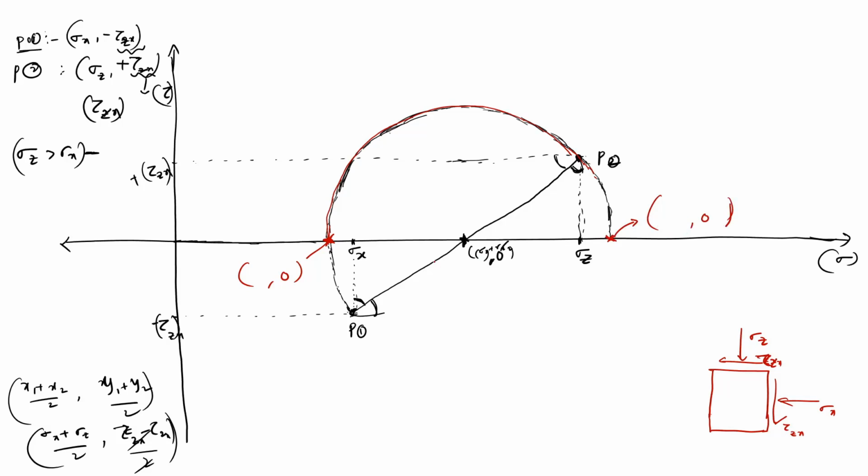So these two normal stresses, the x coordinates of these, should become principal stresses because shear stress is 0. Anyway, sigma 1 and sigma 3 are the principal stresses given in the question. Sigma 3 is minimum, sigma 1 is maximum, the major principal stress, and this is the minor principal stress.